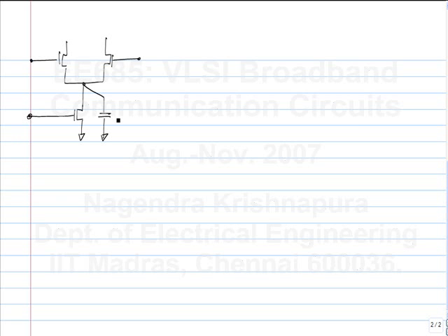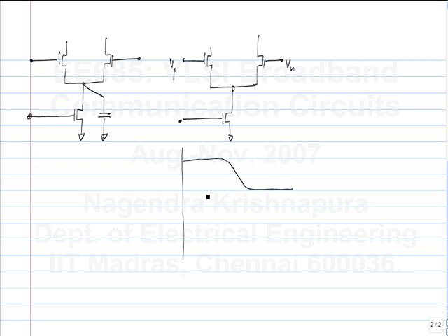It's actually hard to analyze a dynamical nonlinear circuit like this. So first what we'll do is, let's take a case without the capacitance and then say that Vp and Vn vary this way. So basically they have some switching waveforms. So this is, let's say, Vn and Vp. What does V tail look like? Will it be constant throughout? Yeah, this is at its minimum when Vn equals Vp. Is that known?